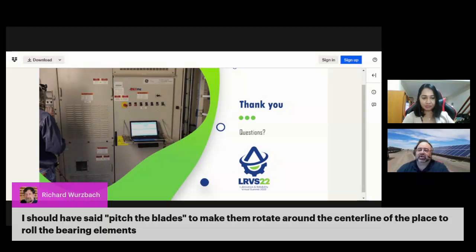That shows up as what's called a blade pass frequency. And if you don't have the resolution, it mixes right up with what's called a pole pass frequency, which is the indicator for rotor related problems. One of the indicators. There's four indicators we need to detect rotor problems. It's a little more complicated than a motor or a generator. That's one of the reasons why we're the only technology of this type that's in the wind industry right now.